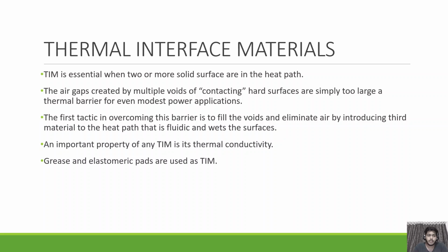Thermal interface material: we are using some kind of thermal interface materials, which can also cool down the system. The TIM is essential when two or more solid surfaces are in the heat path. Whenever we are cooling with the help of air, we need solid surfaces. At that time, we need thermal interface materials.